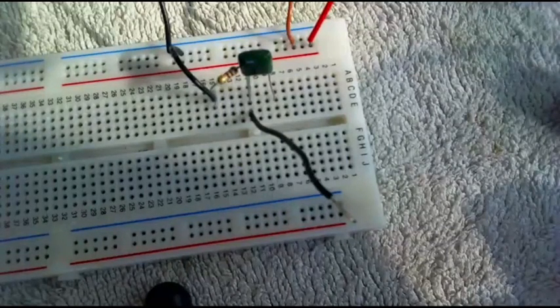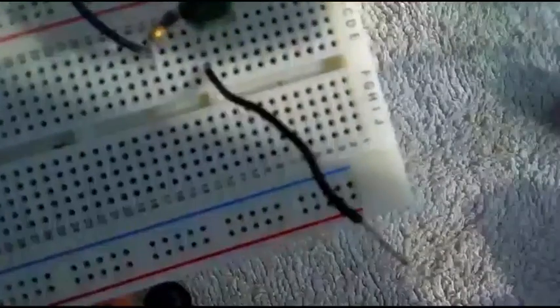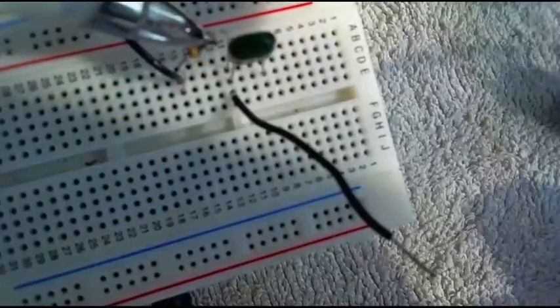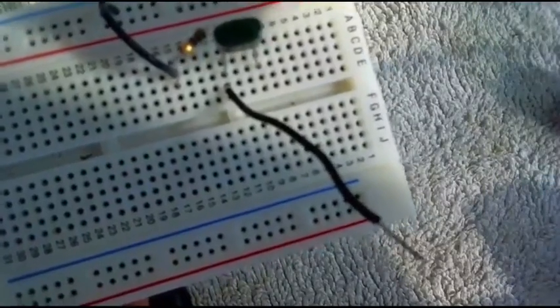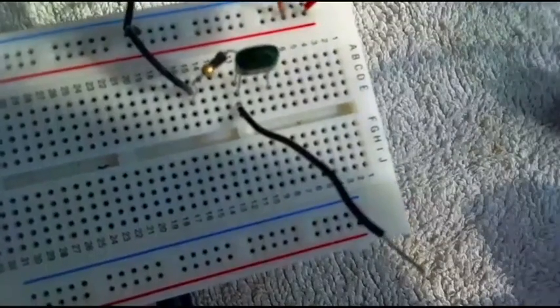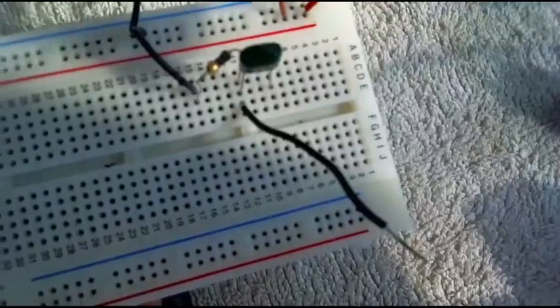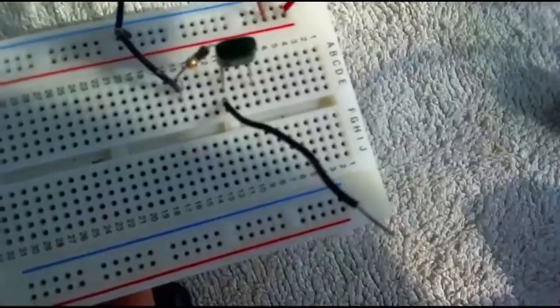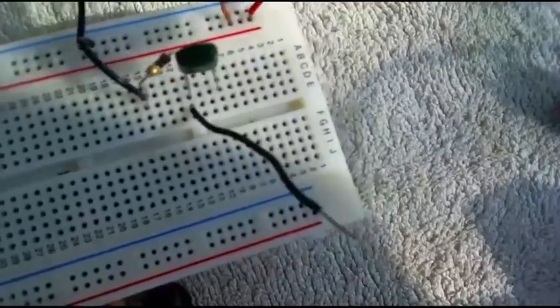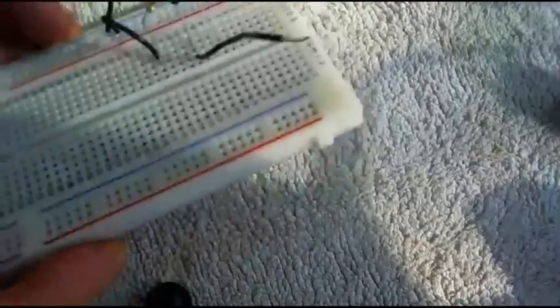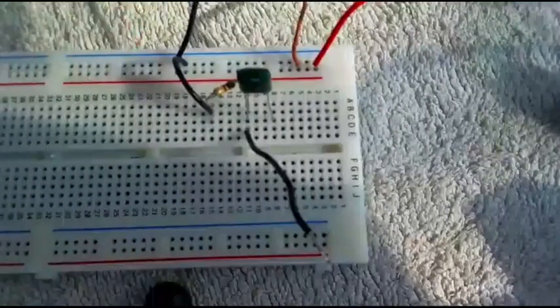Then I'm going to switch back to my scope, and I'm going to look for the place where the voltage signal for the whole circuit and the voltage signal for the voltage drop over my resistor are in phase, because we know that in a series resonant circuit at resonance, all of my inductive and capacitive reactance cancels out, and so there's no phase difference between the whole circuit. The whole circuit becomes purely resistive, so there's no phase difference between the whole circuit and the voltage drop over the resistor. So that will help me confirm the exact frequency of resonance.